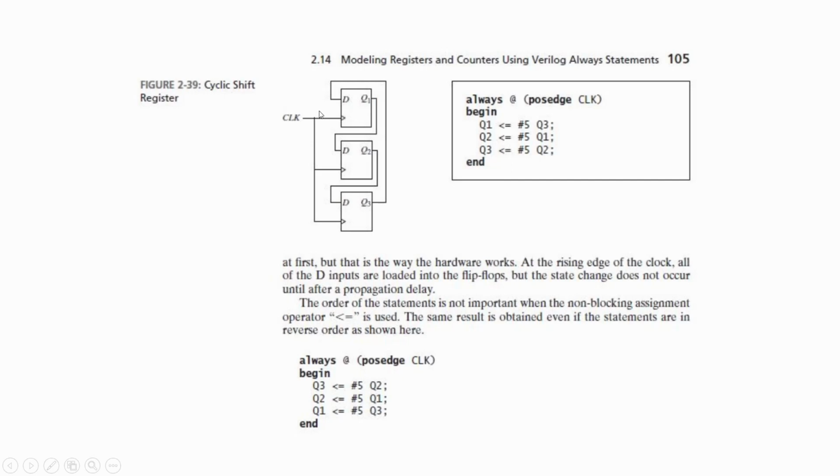That is the reason why we use a clock pulse. For the next clock pulse, when this input is 0, the first flip flop will be turned off. So Q1 will be 0, and the next input D, when it is 0, Q2 will be 0.